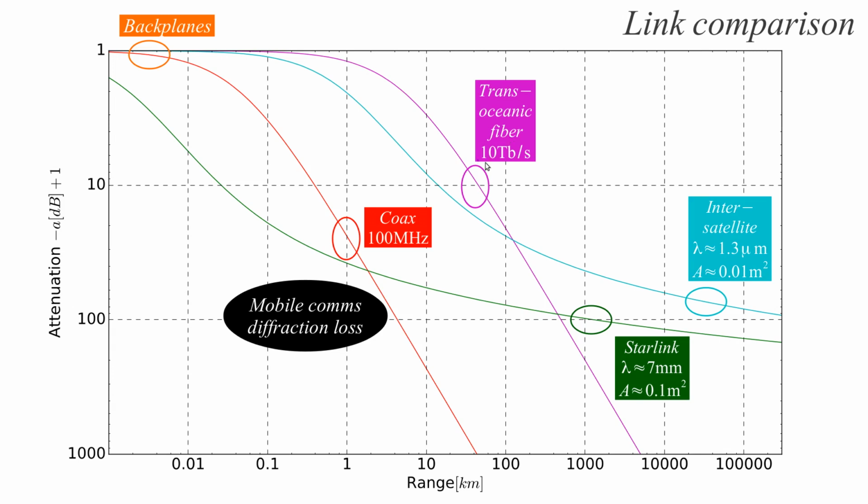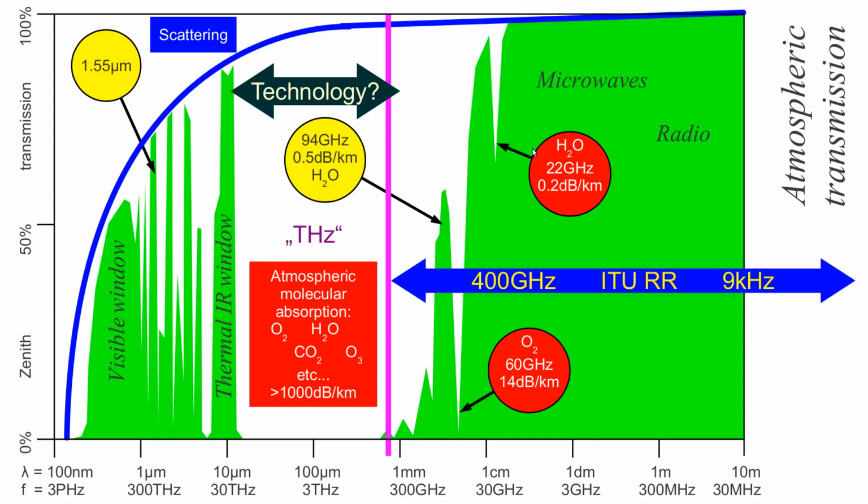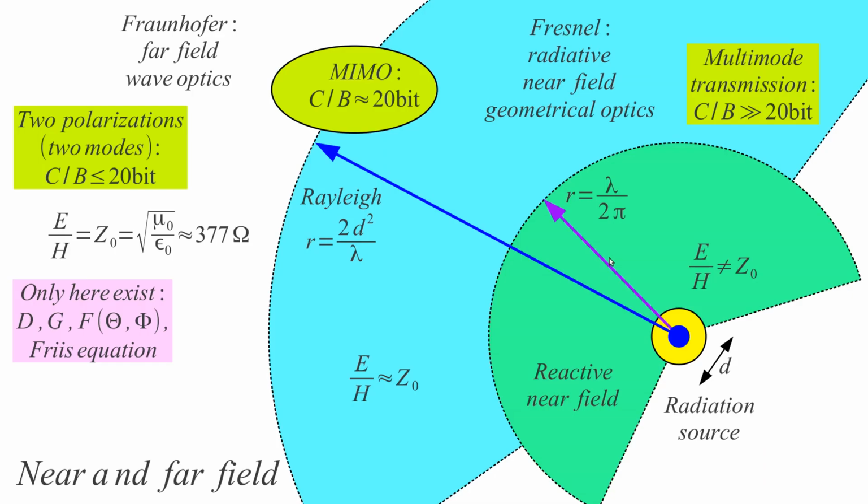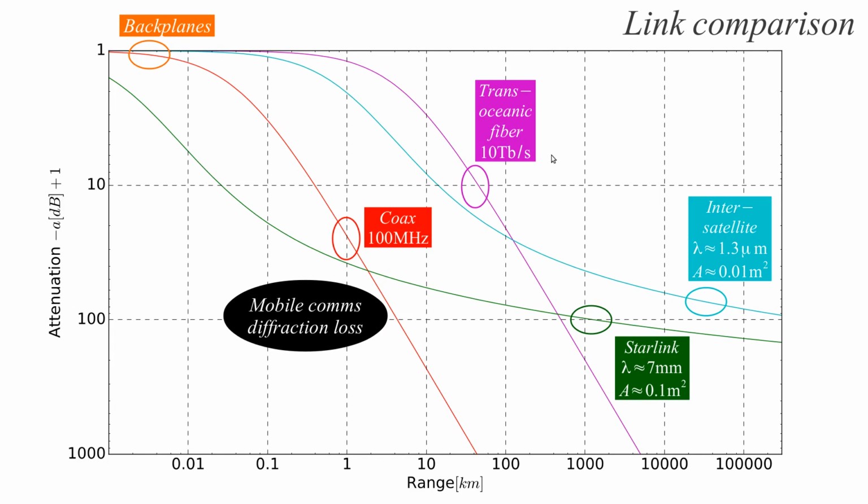According to the bandwidth, we have about 4 terahertz of bandwidth. This 4 terahertz of bandwidth is related to the minimum attenuation here, and it translates into about 10 terabits per second of capacity. So very high capacity for this link. Nowadays they are using more. They are using also 20 terabits. Very complex modulation schemes to overcome the many other limitations of the optical fiber.